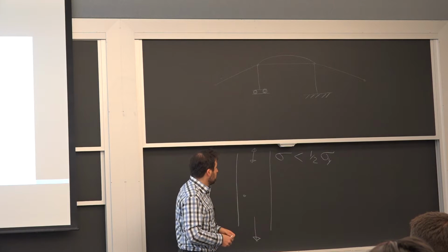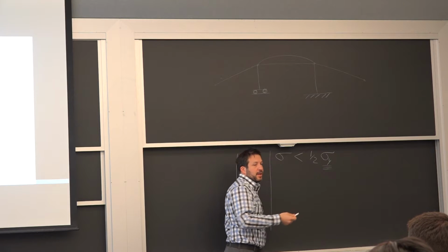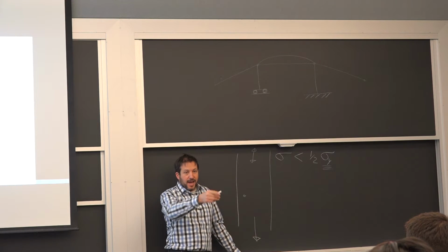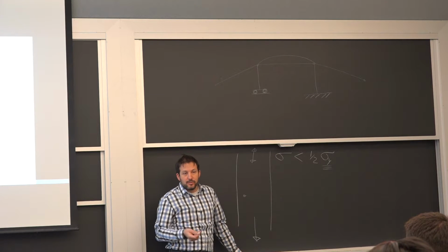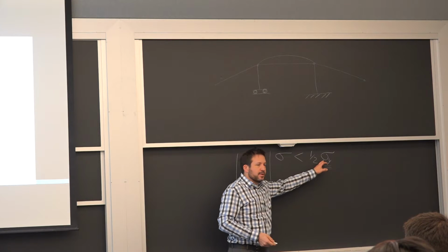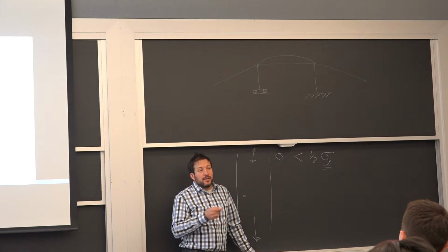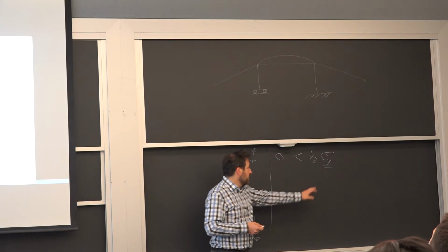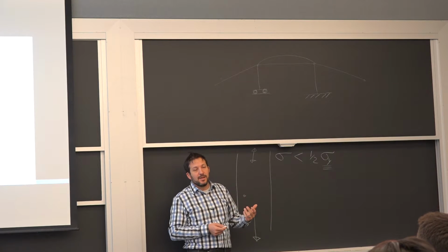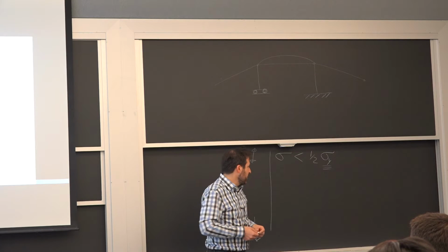Now, essentially for crack initiation, you want this to be high. And that's why we do surface treatments a lot. And that axle did have a surface treatment that just didn't work. But that was the idea, to raise the surface yield strength so you don't have that crack initiating. The real downside of doing this is a lot of times your fracture toughness, so your resistance to a crack, is going down. And there is no perfect solution.